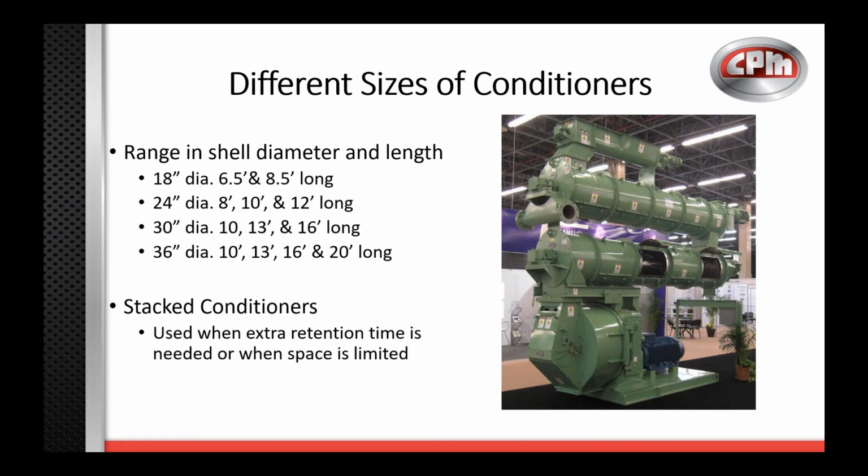If you have space restrictions, for example, if you're running a large capacity and a longer conditioner doesn't fit in the space that you need it to, we can go to some shorter conditioners, two of them, and put them on top of each other to still achieve our goal of retention time.